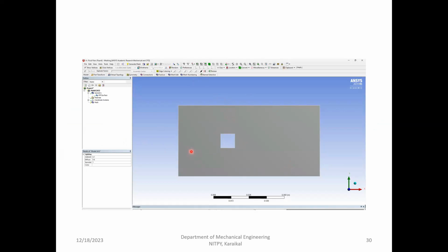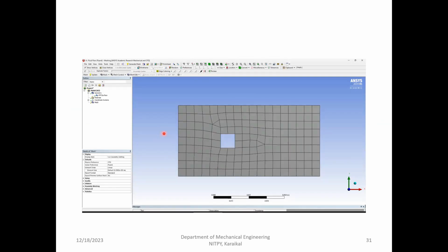For first timers, Fluent is going to work on the fluid. So you have to model the fluid, and then you can have the solid as boundaries. When you talk of pipe flow, we must model the water inside the pipe and not the thickness of the pipe, unless you are going to consider heat transfer through the pipe, those kinds of problems. So now if you ask Fluent to do a mesh, this is what it gives.